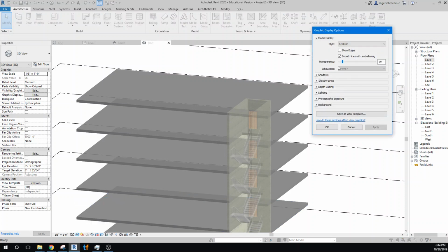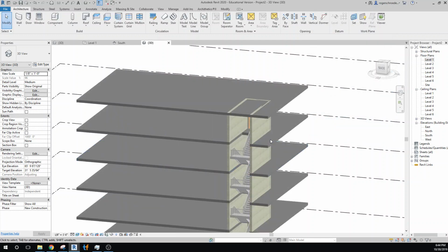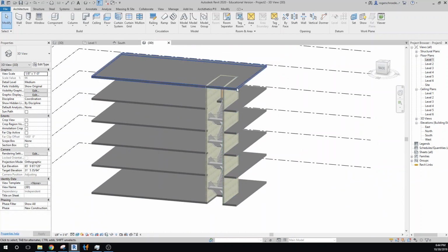I guess one of the most important things about this is this idea of seeing this whole thing as a shear plane. What I mean by shear plane is that once you put this large massive wall system through all these 4 plates, it helps to support the structure, so these can't topple over like a house of cards. And the other thing is that the shaft wall now is lined with fire-rated or could be a fire-rated assembly to protect the occupants during egress. And that same characteristic is going to carry forward when we talk about vertical transportation when we're involving an elevator system.